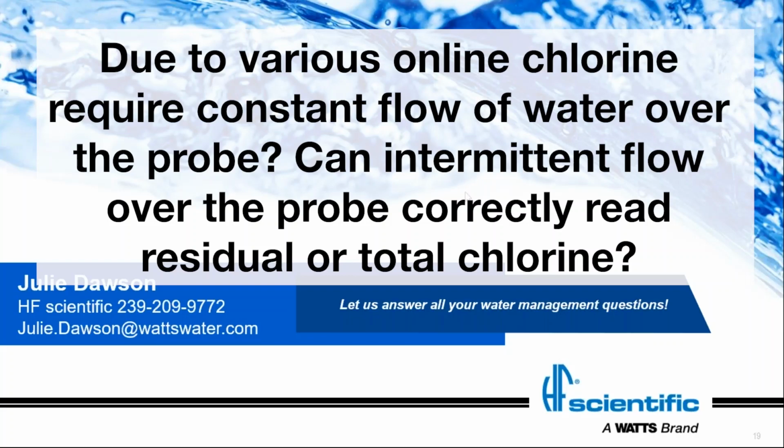So we want to keep a constant flow, and we want to calibrate again if we're going to take the sample off and then put the sample back on. But oftentimes if they're sitting dry, it's going to kill the probes, both the chlorine probe and the pH probe for amperometric if they're not laid up appropriately. For DPD, you actually can allow the analyzer to just not run for some time period and it'll come right back up and run well.